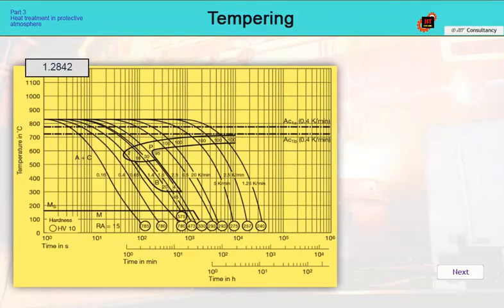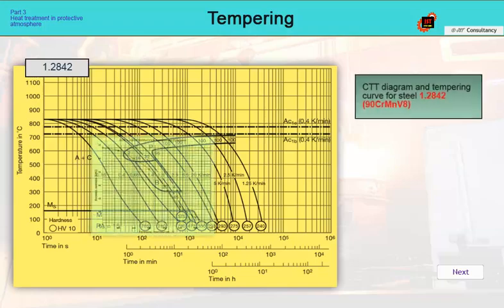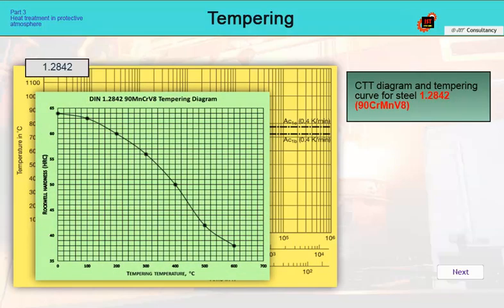In the previous section, we determined the tempering time and the number of tempering cycles. We now need to determine the temperature. In order to properly perform the tempering process of steel, we need to know its tempering curve. This is another diagram that is developed and known for each steel. It is usually in the form shown in the figure, where the dependence of the decrease in hardness on the tempering temperature for defined times is shown.